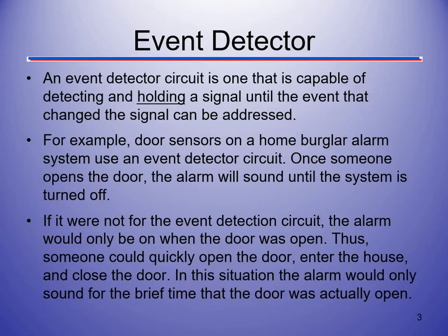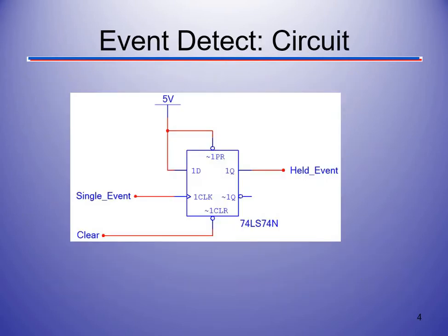Your smoke alarm is going to sit there. It's going to detect smoke and continuously go off until you go reset it. At school when we have a fire drill, or a real fire for that case, the fire alarm goes off. Consistently it has an audible and it has a visual, right? And the only way for us to stop that from continually going off is someone has to go reset the alarm. So that's an event detector. It detects the event that's going on and then it holds that in until someone does something about it, okay?